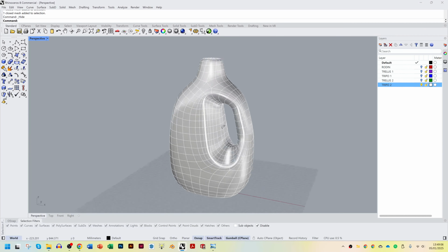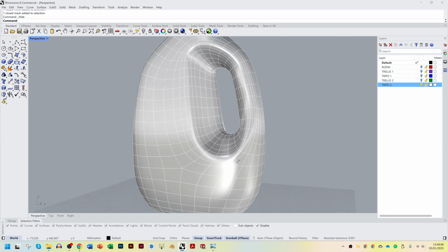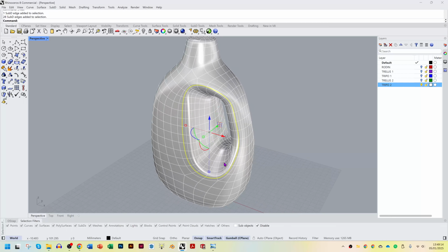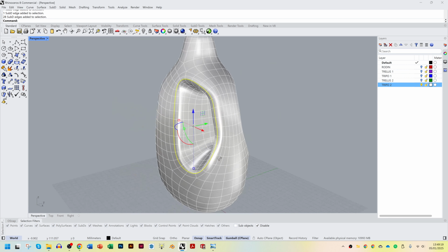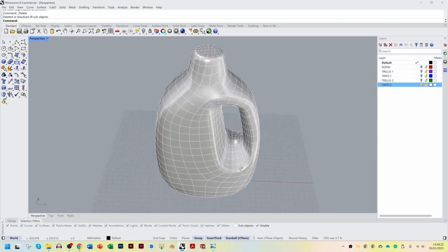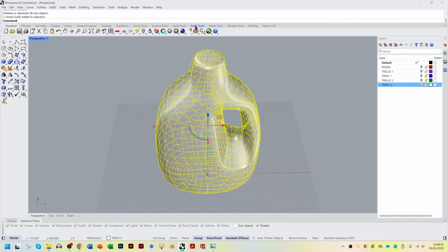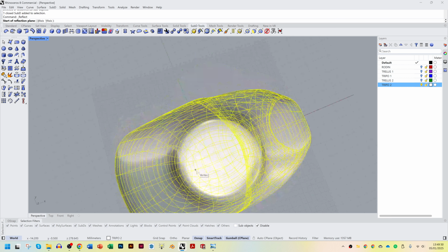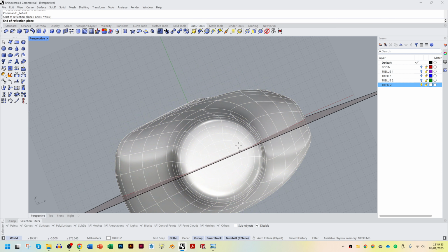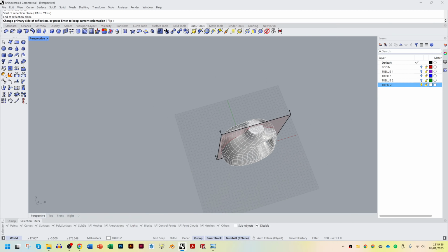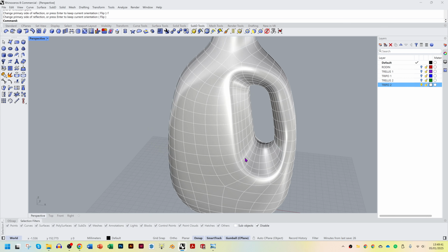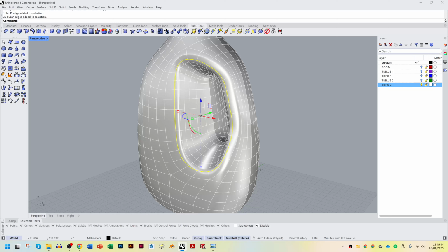Once you've got to this stage, there's still work that you might need to do here. Oh, that's good. It let me pick that as a loop, because I think I want to delete that to soften it a bit, and I want to delete ideally another one. It is letting me do that, which is nice. Let's turn our symmetry on here, so that when I'm doing that, I'm only doing the work once. If I turn on reflection plane and use vertexes here, vertex to there, flip that because I want to keep that side. So I've just deleted a couple of edge loops in there to soften these edges. That's working really well.